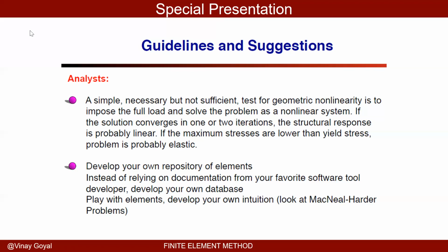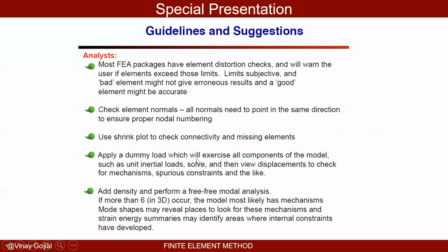Okay, next chart. Hey, Raju, I want to make a point about this slide. Some students had a homework project, and they're getting 6 rigid modes. Basically, six frequencies are close to 0. And they're asking why is that? That's because the model was not sufficiently restrained for that particular problem. So you could do an analysis that's free on purpose, but you could also do an analysis that's fixed with the correct boundary conditions to understand the model frequencies.